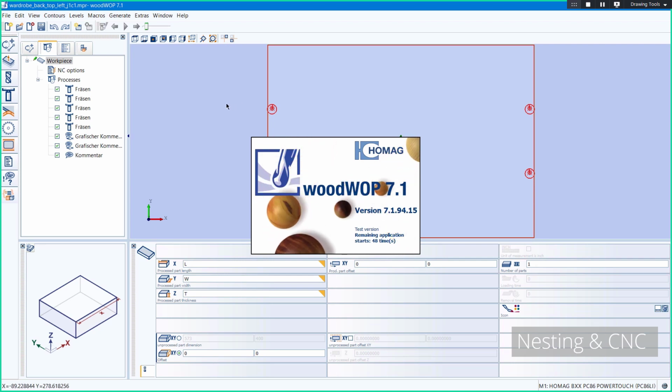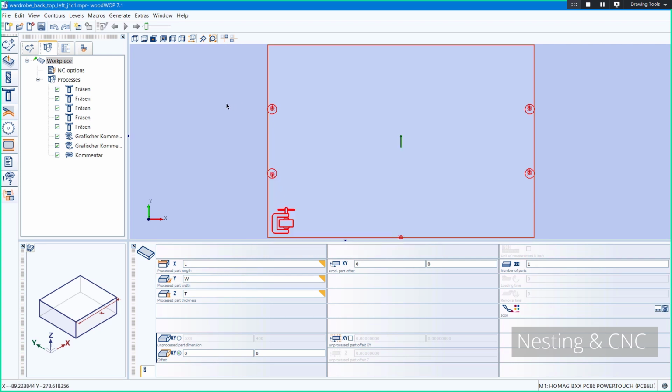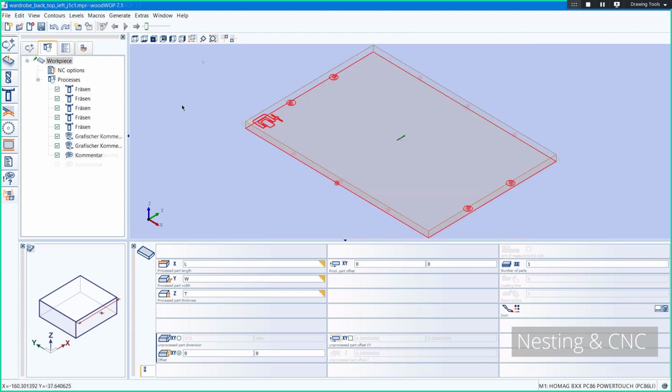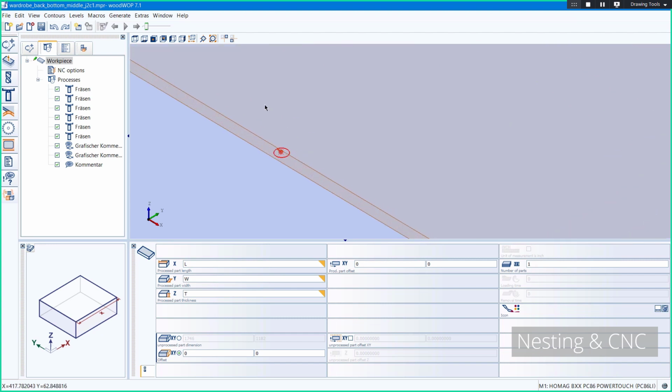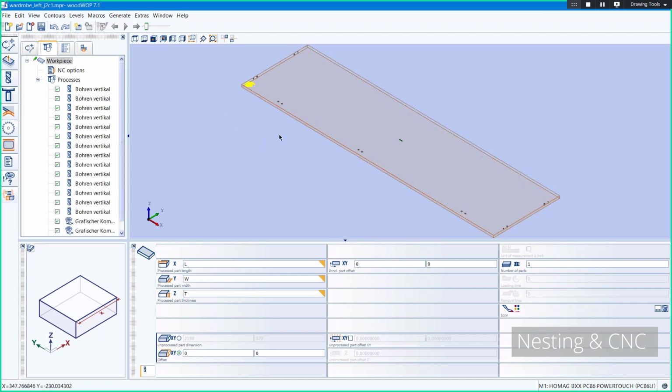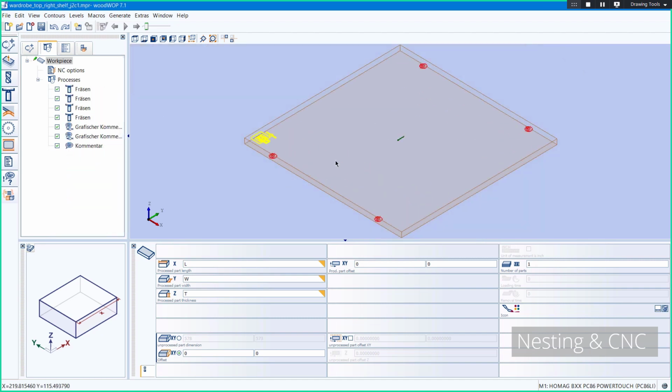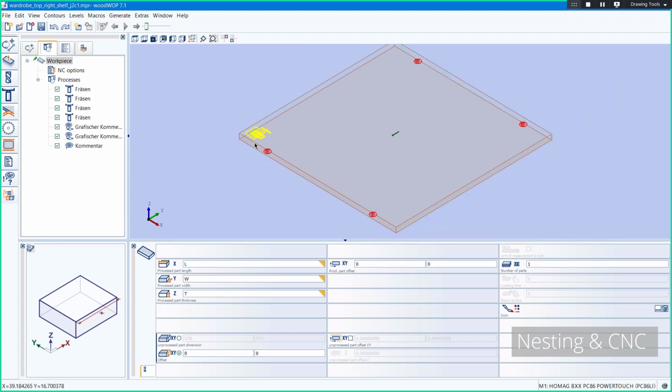What you can see in the file actually depends on the extension. Some of the files allow you to have some additional information, some of those not. But in this case, in Woodwork, you can see the grain directions, you can see edge banding, you can see a clamping point and the condition of what you're placing on the part. Is it a part or is it a workpiece with covers or without covers? So your CNC operator can see it on the screen, so there is no room for mistakes, because if you read the drawings you can always make a mistake. But if you look at the screen of your machine, there's no chance to do something wrong.